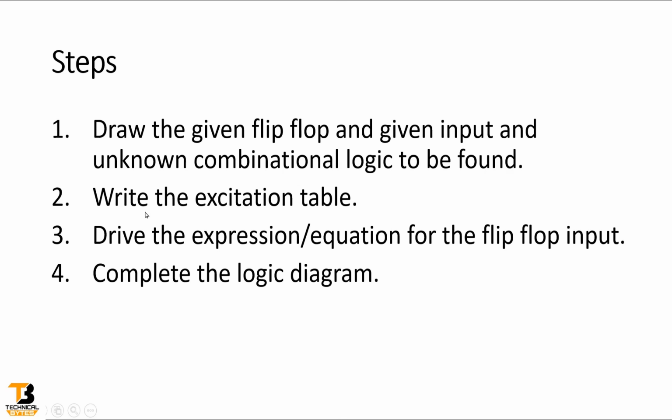Second step is you have to write the excitation table. You will come to know soon. And the third step is we have to derive the expression or equation for the flip-flop input. And the fourth step is, after knowing the equation or expression, we have to complete the logic diagram. Now let me reveal all these 4 steps by taking some examples.